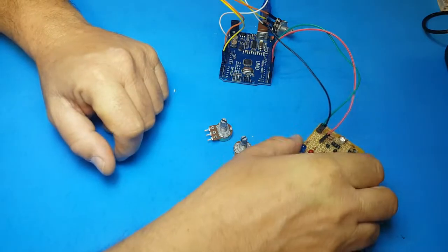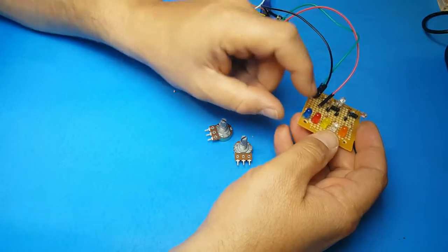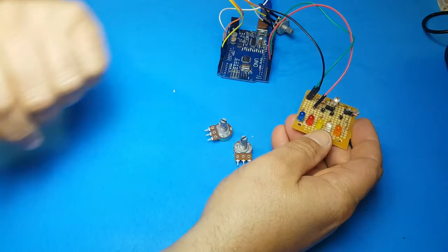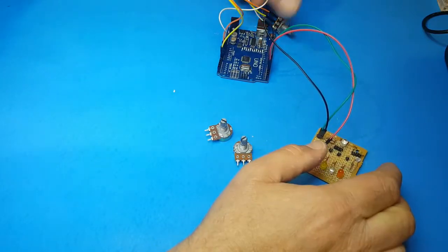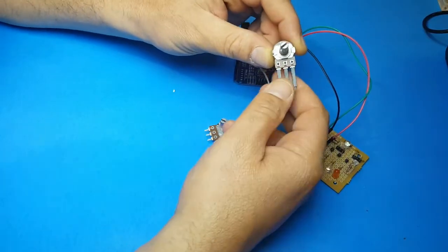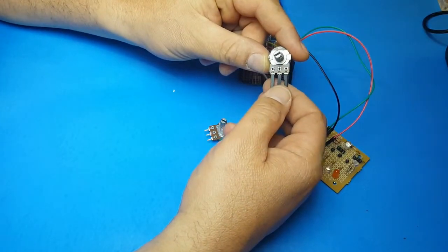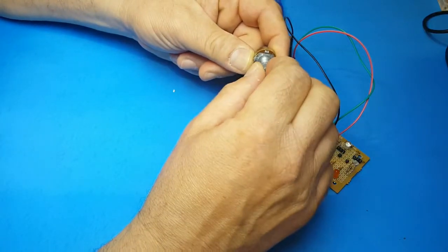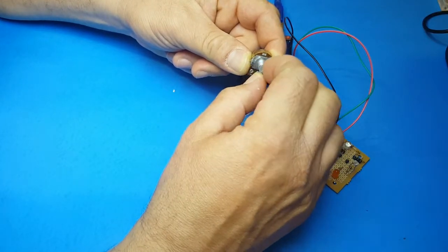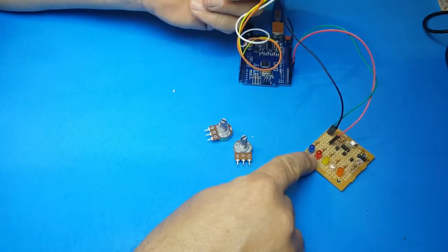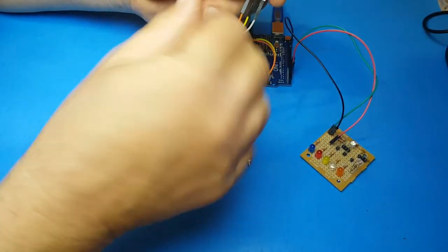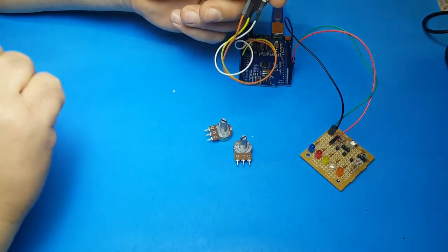Now, the two LEDs are the red and the blue one. These are the two I'm going to be using for the sketch. They're going to be connected to a 5 kilo ohm potentiometer, which is the same thing as a resistor, but variable. When I turn the potentiometer in one direction or the other, in other words by changing the resistance on it, one of them will become brighter while the other one becomes dimmer. And if I turn it the other direction, it's going to be the opposite.